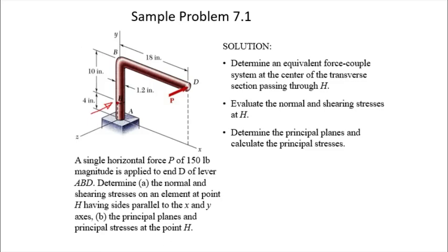And point H has sides parallel to X and Y axis. So when we take the stress element it will be parallel to X and Y. So our stress element will be something like that. And we look at it from Z direction. Okay, we look from Z here. And we look at the stress element right perpendicular onto the face. Okay, and then it asks us to find the principal planes and principal stresses.